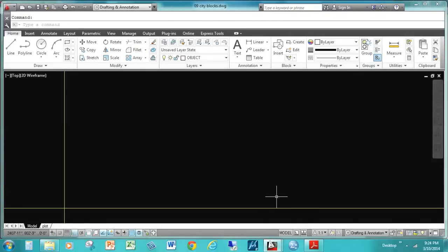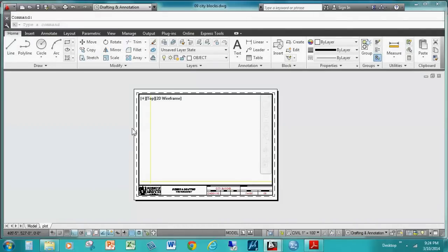So in our class assignments folder, there will be a DWG file with number 9 that we need to use to draw the object. Now, up to now, we've been drawing the objects in model space, and printing in model space because we've had the drawing template right in model space. Today, we're going to draw all the objects in model space one to one, then switch to the plot tab, which is the layout space, also referred to as paper space.